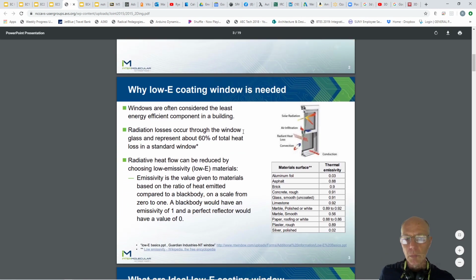And their intention is to block this idea of radiant transfer through the windows. In most cases, depending on which surface is coated, it's intended to usually block out solar sunlight radiation from entering the building and adding additional heat. But it also can be very effective in cold climates coated on the right surface to prevent radiant heat losses from the inside of the building.